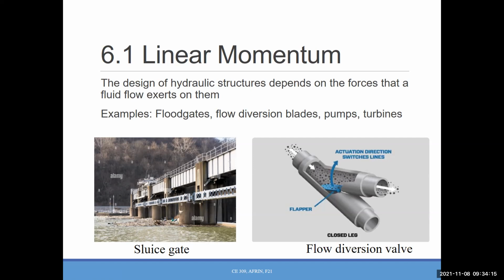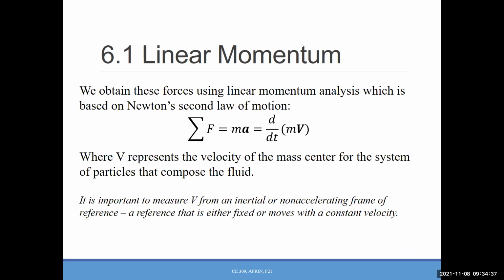If you want to protect the lower-end people from the flood, you can use this gate and it will hold the water for a certain time. Then you can release the water slowly so that there will be no flood downstream. That's why it's also called the flood control gate. To design those, we need to know the force, and that's when we need the momentum equation.